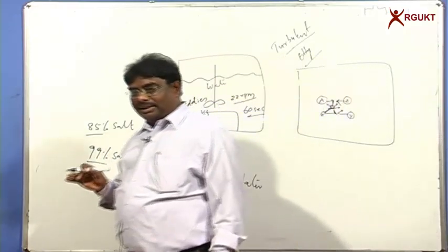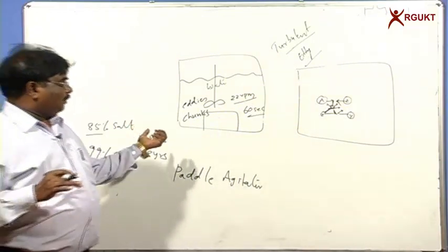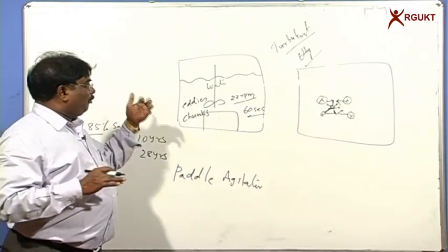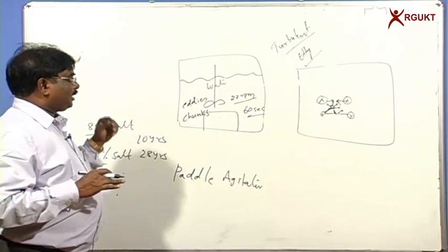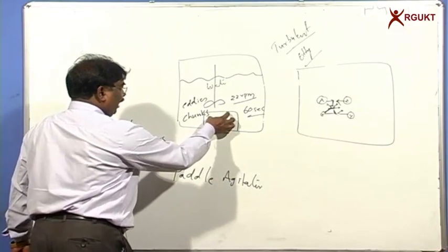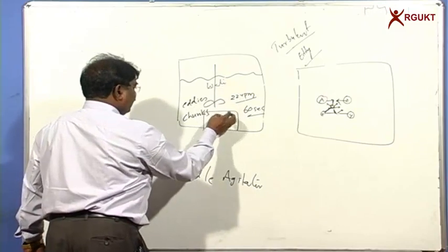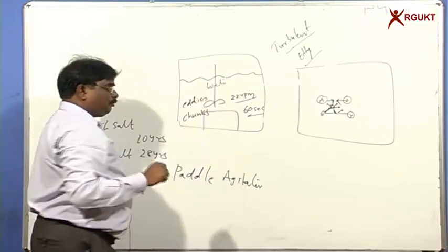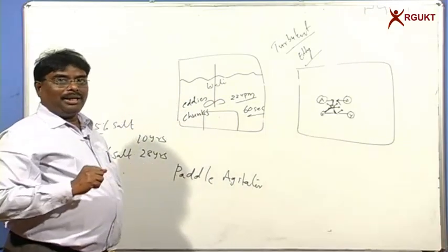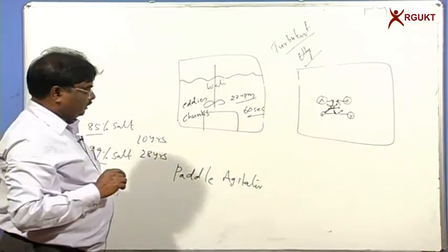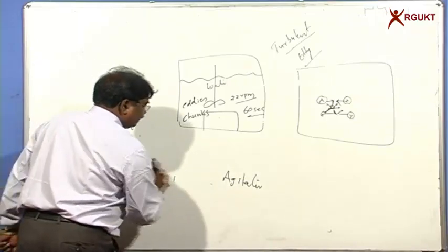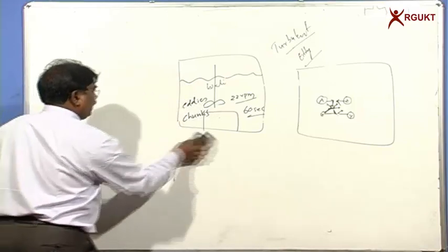It gives you the importance of turbulent flow in mass transfer operations, and that is where we have to understand momentum transfer when we want to clearly understand mass transfer operations. Till now, what we understand is, here we have a salt, here we have water. There is a high concentration of salt here and a low concentration there. The salt is moving from higher concentration to lower concentration, and ultimately the system is going to become a uniform concentration. But to tell you, sometimes concentration is not the driving force for mass transfer operations.